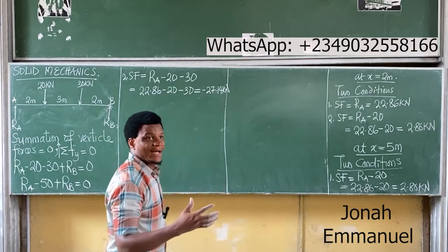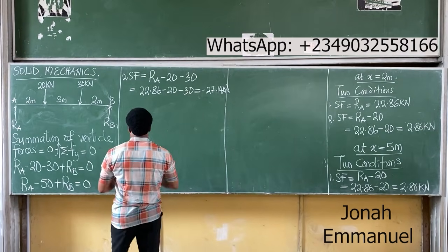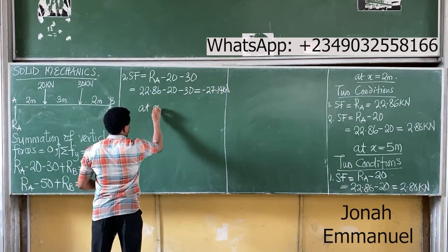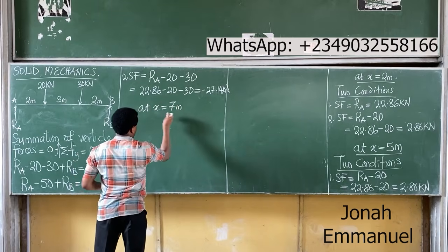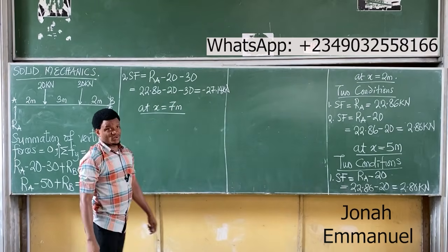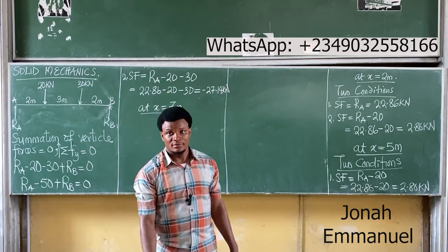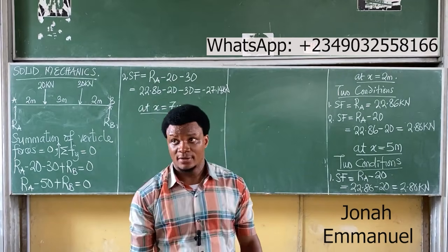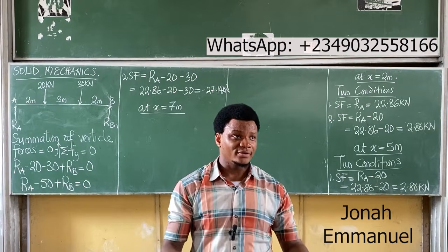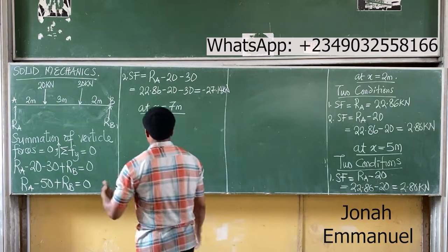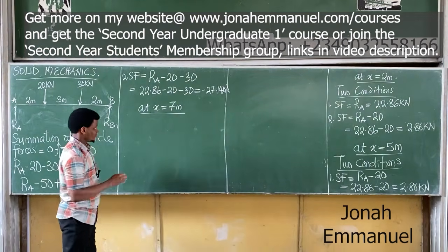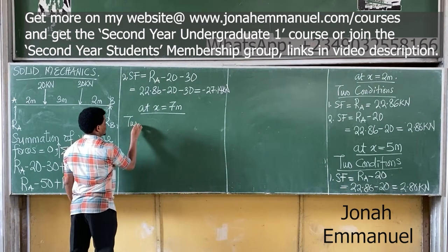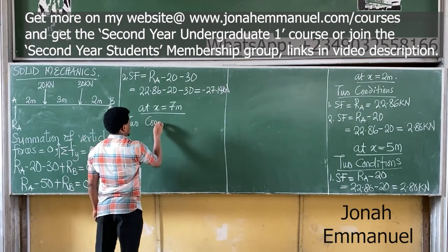At x equal to what there? 7 meters. Please, do we have a point load at 7? Yeah? Okay, so what do we bring in? Two conditions. Please don't forget the two conditions first.